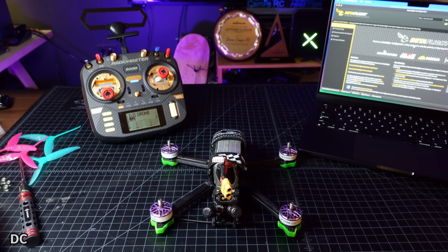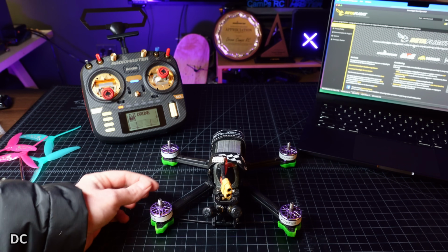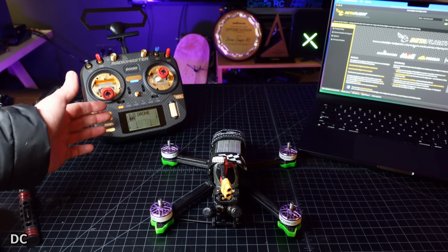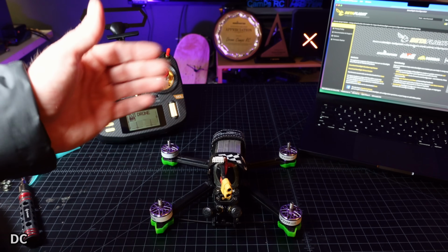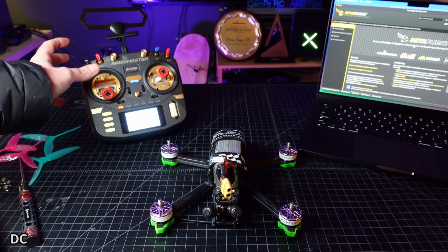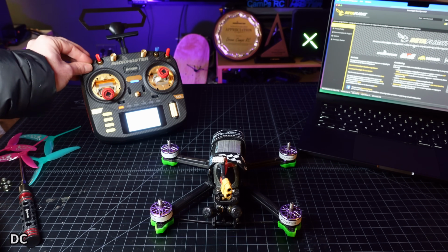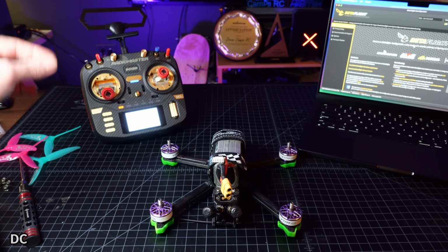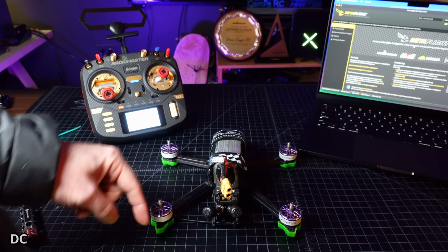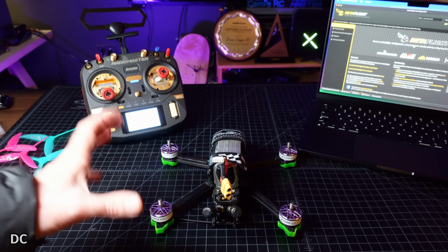What you're going to do is take a little bit of piece of painter's tape and put it on the top, and you're going to create like a little bit of a flag off the top of the motor post. Turn on your radio, plug in your battery, gently arm the quad, and disarm the quad. So you're going to basically flick the arm switch on and off, and that'll spin up the motors enough in air mode that you just get a little bit of motor turn, and it should show you which way your motors are turning.